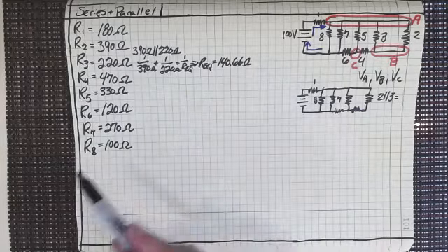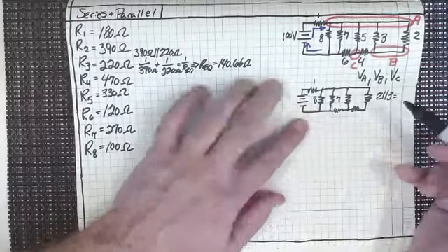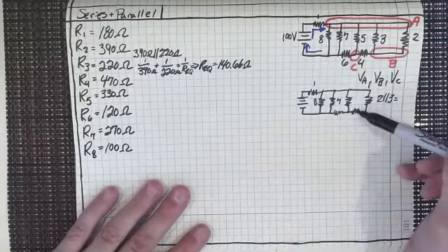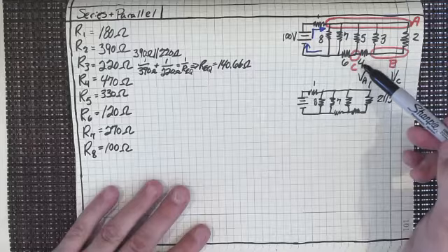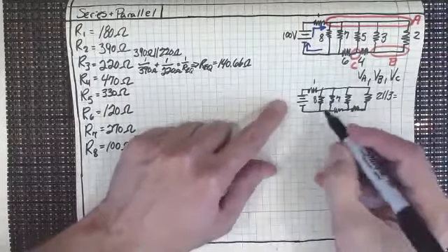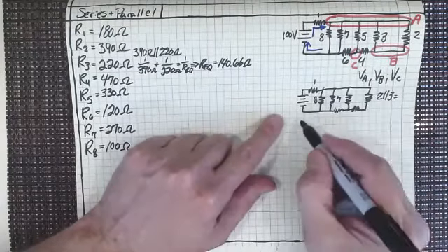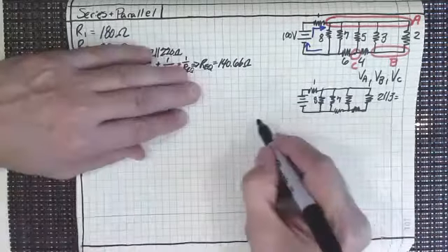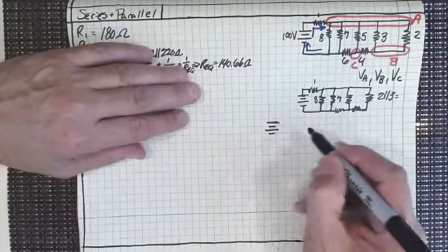That's sort of what you're doing. The more experience that you can have with solving problems, seeing how they're solved, putting these things together, and of course we've got that now. But hey, look at this. We've now got that, the 140.66, in series with R4, don't we? It's in series with that. So now we can redraw this again, because we'll have this in series with that, and I could draw it as, God, I hate to keep drawing these, but I will. And my pen is getting less too.